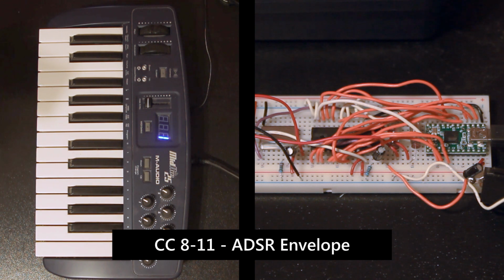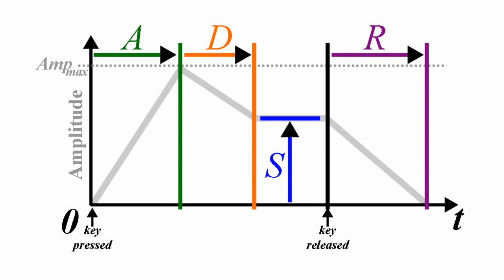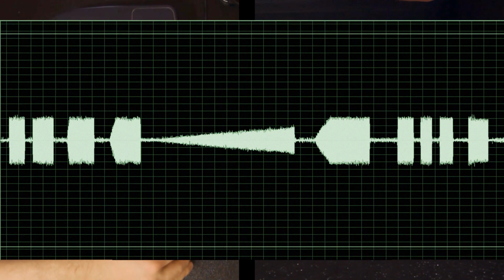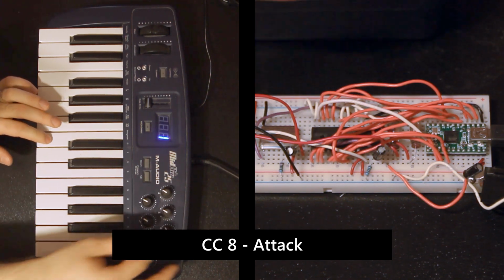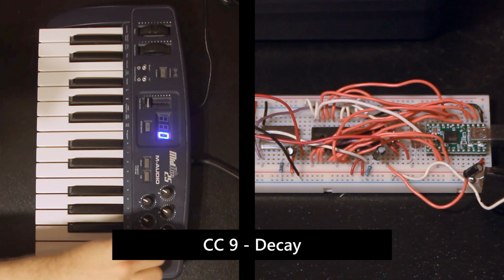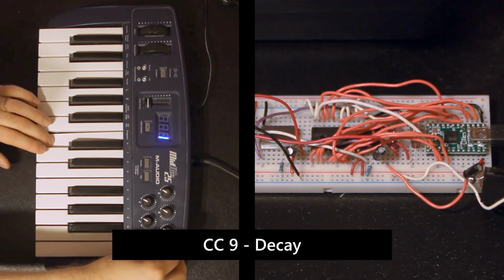One awesome thing about this chip is that it has an ADSR envelope generator built into each oscillator, so CC8, 9, 10, and 11 control the attack, decay, sustain, and release of the oscillator. Here's an example of a fast attack going to a slow attack and back again. Here's an example of a fast decay going to a slow decay.